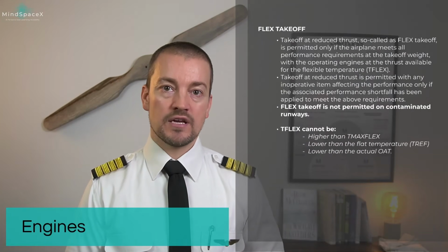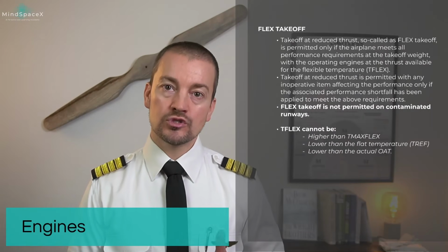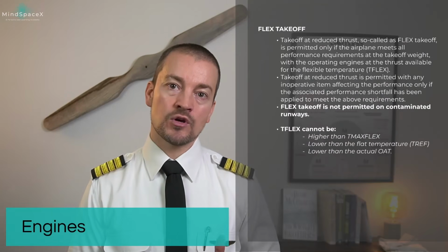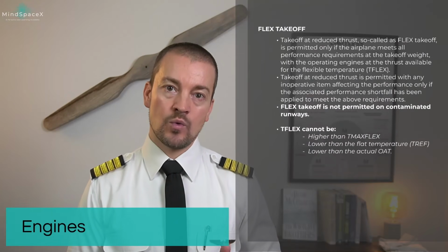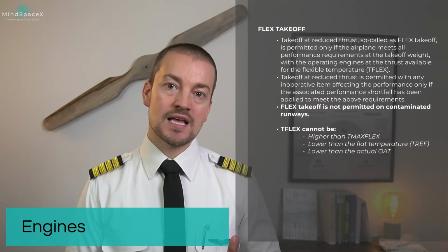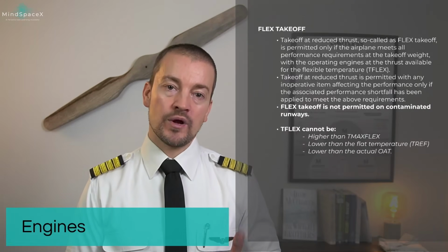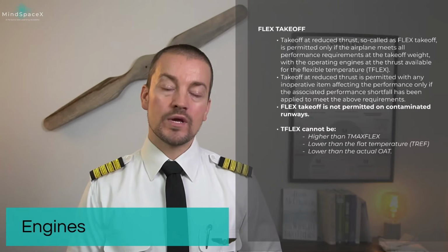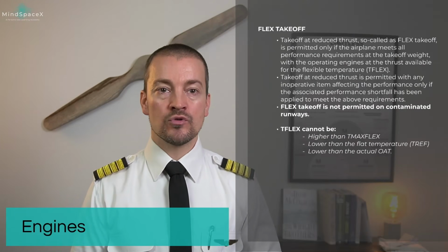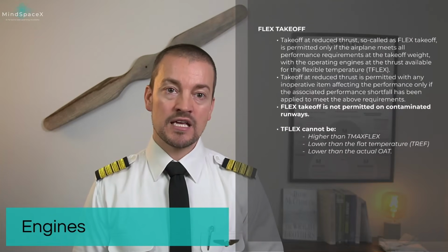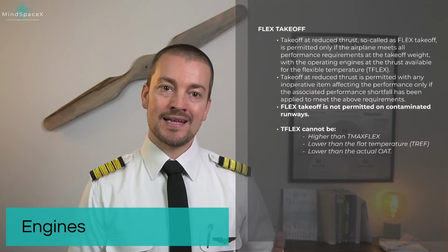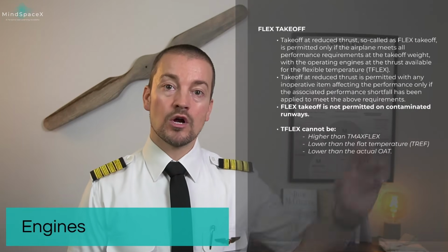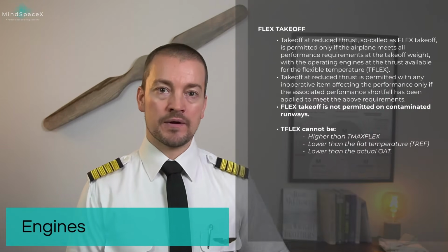Flexible takeoff, that means takeoff on reduced thrust, is permitted only if the airplane meets all the performance requirements at the takeoff weight with the operating engines at the thrust available with the flexible temperature set, T-flex. We calculate this when we put the values for the current conditions into the EFB, or when we manually calculate it from the FCOM takeoff tables to ensure we do meet that requirement.